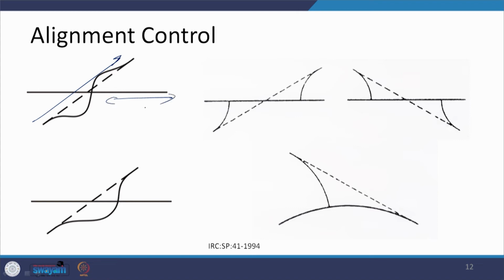As we talked about, as far as possible the roads should cross each other at right angles, so that is what we have tried to ensure at this point. We have made a small change. The traffic coming from here, some distance ahead of this crossing itself, the profile has been made such that the visibility is there up to this point, as well as for this. So, this is the total area which is going to be visible on the basis of this adjustment.